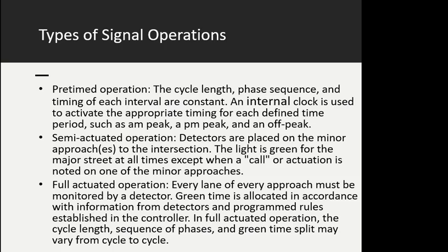Okay, and the next green cannot be before 30 seconds. Okay, so we fix these ranges. We fix how much should be the first green interval, we fix how much should be the extension in the green interval, we fix how much should be the maximum green interval for the minor road.